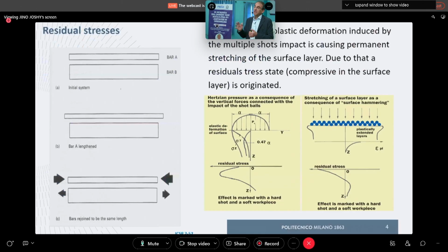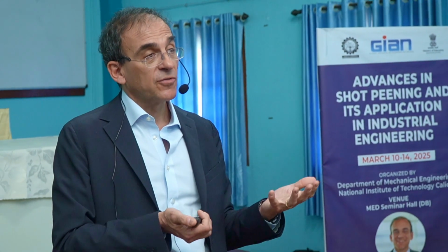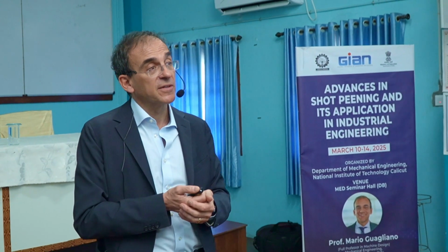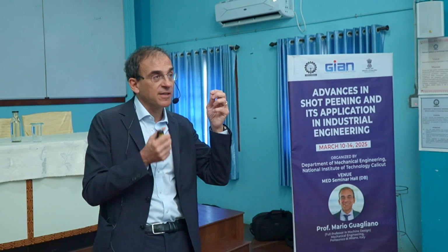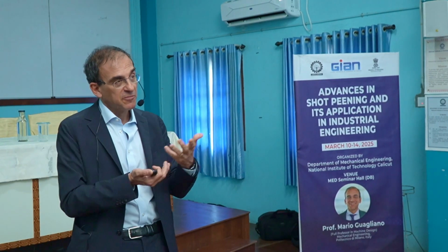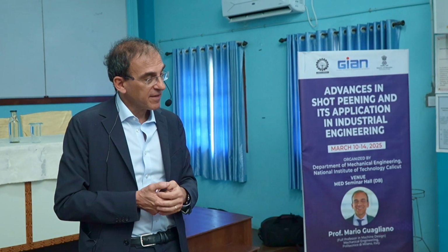At least in the linear elastic field as regards the behavior of the material, the constitutive equation of the material. The contact problem is not linear, not for the material, but for the geometry itself. That is to say that the pressure is not varying proportionally to the applied load, because the contact area is also varying not proportionally.